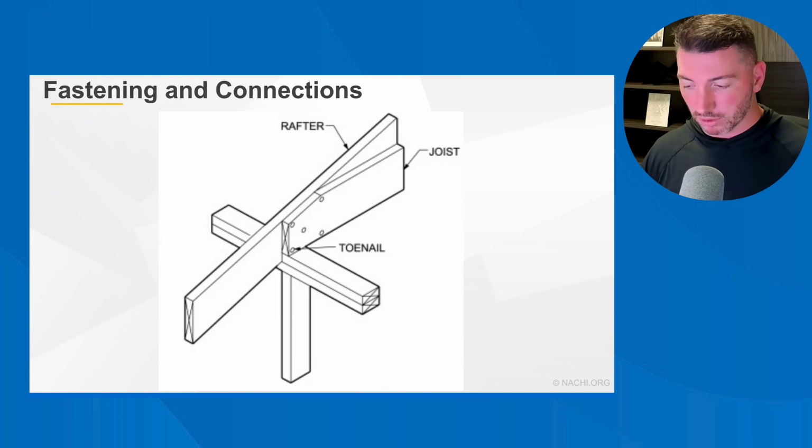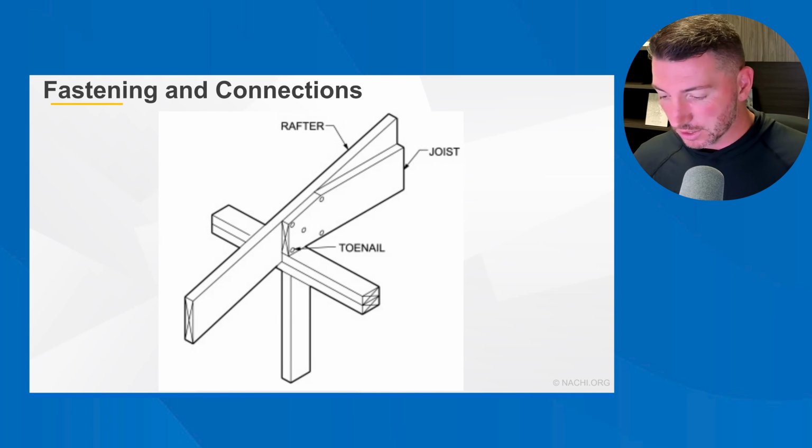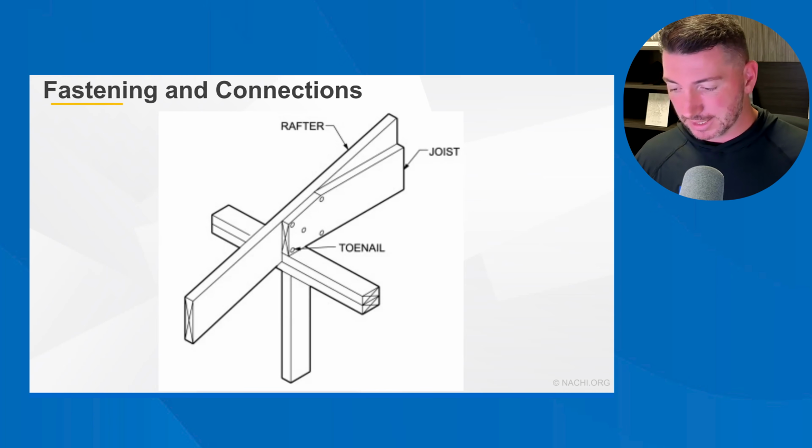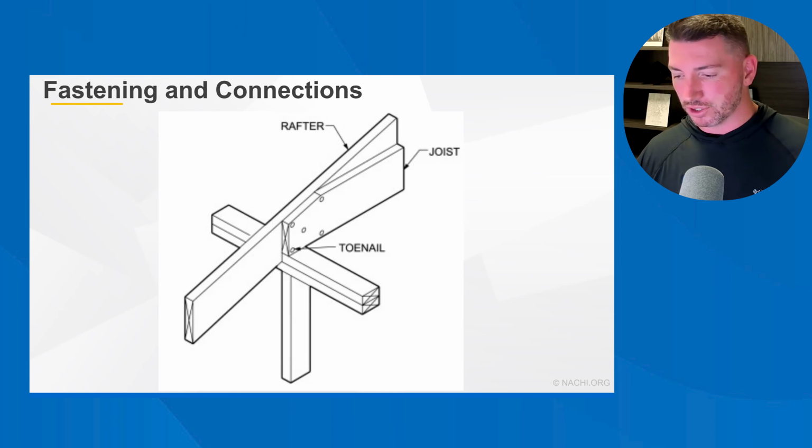And we do a visual only, non-destructive inspection, right? So what you can do is identify obvious deficiencies, right? If there's a missing connector, same thing with a deck connection. If you're missing hurricane ties or you're missing joist hangers, you're going to call that out. So look for obvious issues. And if you're not sure if it's an issue, flag it now, research it when you get home, and don't send out the report until you're sure.